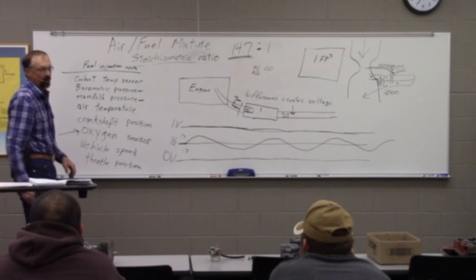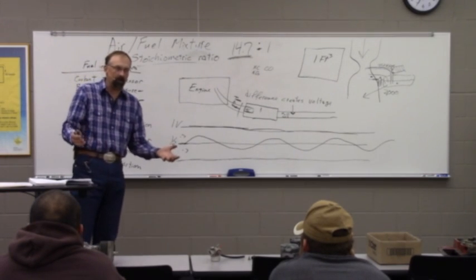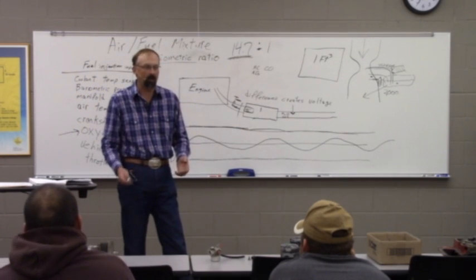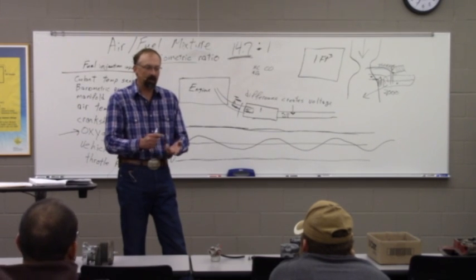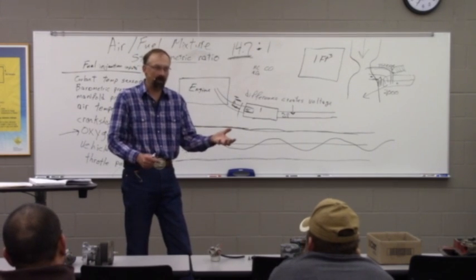So, for example, the avgas that's 102 octane, you compare it to the 85 octane that we might be buying at the pump, there's going to be more available energy in it, and it's also going to vaporize from liquid into the vapor easier.